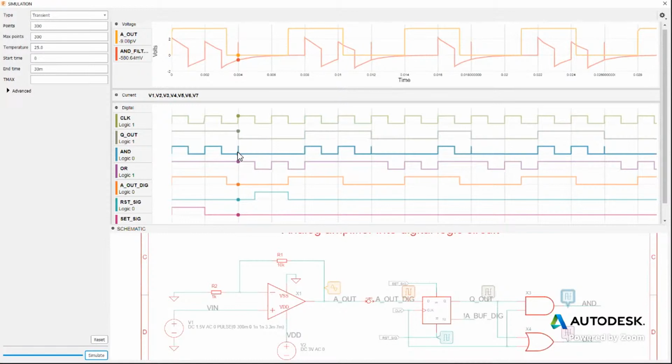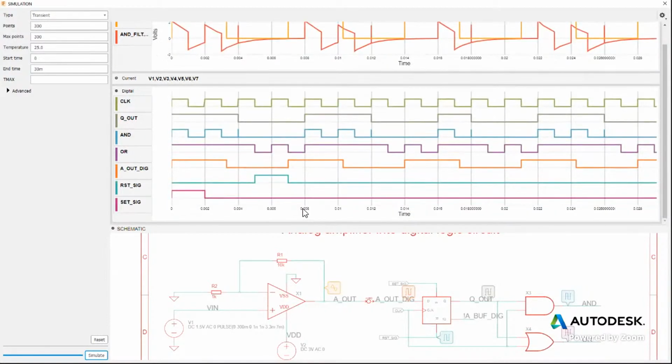Here you have kind of a funky transition where it's kind of indeterminate. So that's something where the simulator couldn't quite handle it very well. Here, because this is low the whole time, this stays low. You can see that in a real circuit, this would be a glitch. Because the reality is that there would probably be some time differential here, some delay, and you may not get that glitch of an indeterminate state. But that's something to be aware of. If they're perfectly in time, what happens here? Okay. So overall, the results are looking like what we expect.